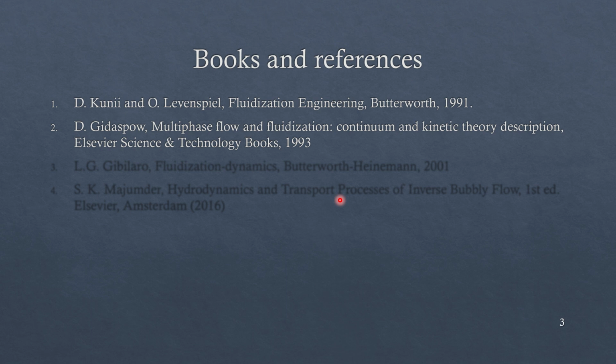But when we are dealing with the continuum theory, it becomes necessary to assume certain properties of the solids such that the kinetic theory description can be applied. So we can formulate the kinetic theory of granular flow similar to that we use for the kinetic theory of gases. Based on that assumption, it is possible to model the particles as a continuum. That is explained well in this book along with other aspects of fluidization.